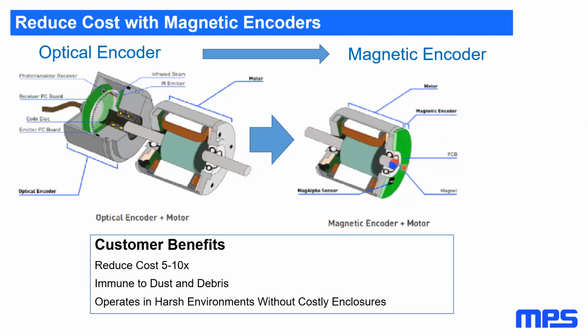This magnet maybe costs, I don't know, 3 cents, 2 cents. The IC here at volume, you're talking around $1, $1.50, compared to this thing that is going to be anywhere from $4 or $5 up to, well, if you want IP, ingress protection, so you don't get dust and dirt in there clogging up your code wheel disk, this thing can literally go up to hundreds of dollars. So the point is, this takes less math, but we're engineers. Let's take 20 minutes up front, do the math, do the calculations, figure out where we need to live, and save a lot of costs and a lot of space.